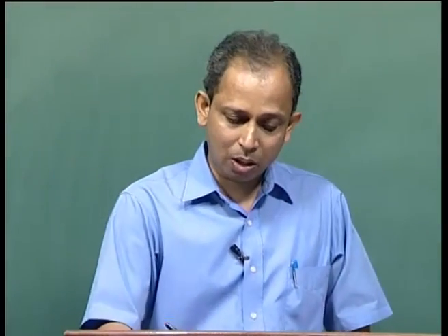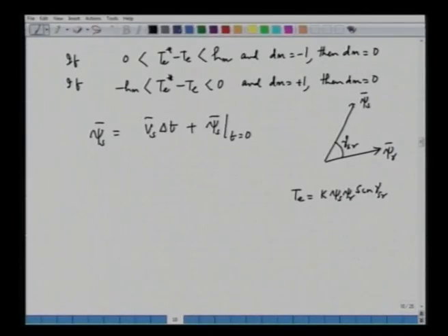And if we do not want to increase or decrease the torque, gamma SR should remain unchanged. So, this flux is frozen. This flux is neither accelerated nor decelerated. So, what we do here, we can do that by applying a 0 voltage vector.